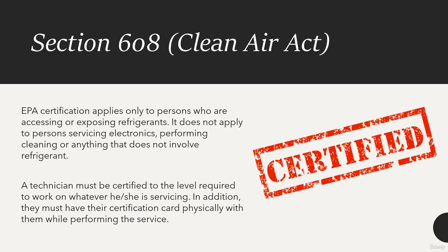EPA certification, Section 608 certification, applies only to persons who are accessing or exposing refrigerants. It does not apply to persons servicing electronics, performing cleaning, or any part of the installation process that does not involve opening up a sealed system or refrigerant charging. A technician must be certified to the level required to work on whatever he or she is servicing. In addition, they must have their certification card physically with them while they are performing the service.